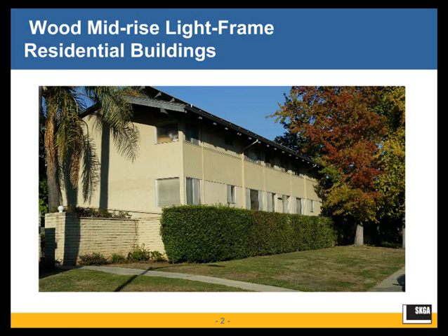Historically, this building type often featured relatively simple plan geometry, regular and not overly extensive exterior fenestration, and, most importantly structurally, a relatively uniform distribution of shear walls of roughly equivalent stiffness. The code provisions relevant to this building type have implicitly assumed these features. Traditional analysis techniques utilizing flexible diaphragm assumptions and floor-by-floor shear wall stiffness distributions were and continue to be adequate to analyze regularly configured buildings of this type.